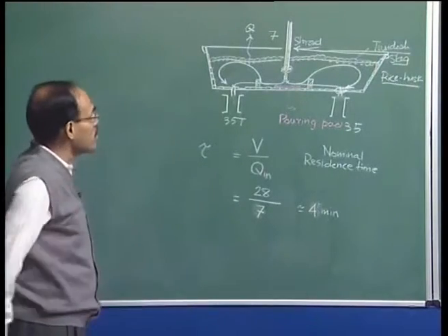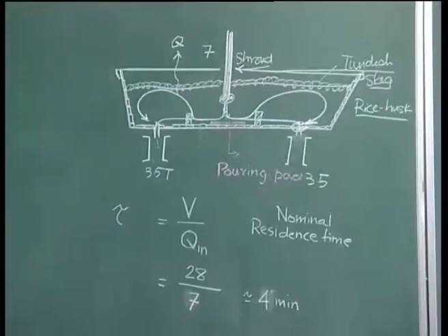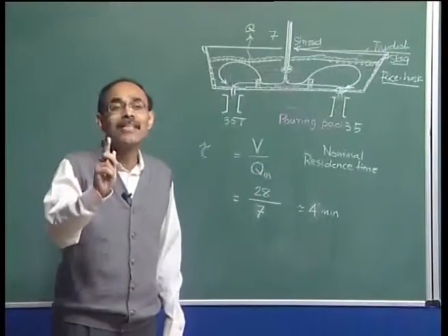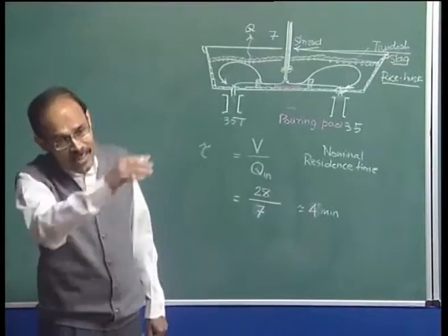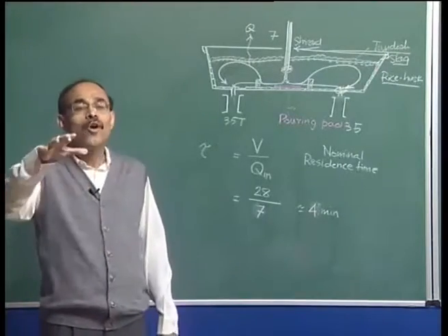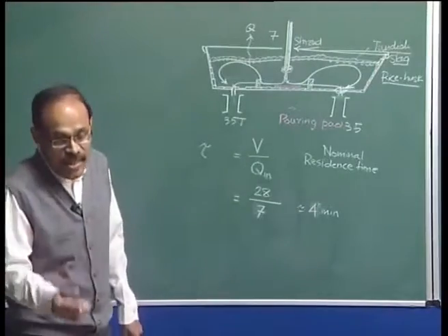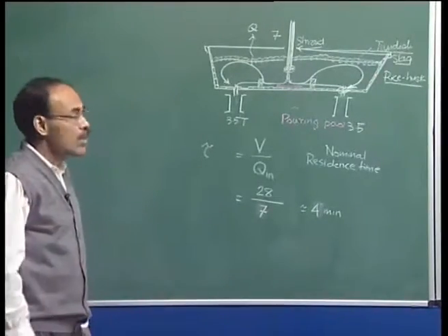and if you are operating without a tundish cover, in that case there could be a much more pronounced temperature drop. I would like to also mention that in many steel plants, in all ladle metallurgy operations, ladles are also operated with physical covers, and this physical cover really cuts the radiative heat losses from the surface of the melt.